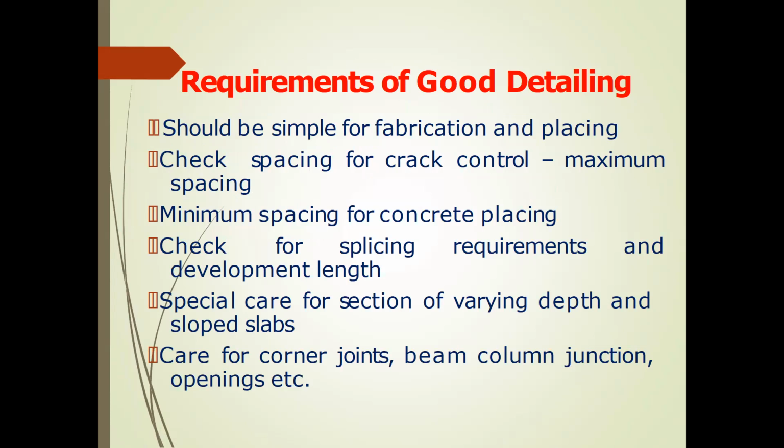Check spacing for crack control, that is the maximum spacing. Check the minimum spacing for concrete placing. Check the splicing requirements and development length. Take care of sections with varying depth and sloped slabs. Take care of corner joints, beam-column joints, and openings, etc.